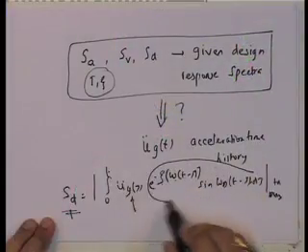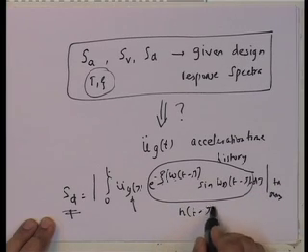So, this is what is known as a classical inverse problem. If you know one thing, finding out the other is really hard. The input is the time history. You have a kind of a box that represents the structure. That is given by h of t, which is the unit impulse response function. H of t is nothing but this, right? This is h of t minus tau, remember?